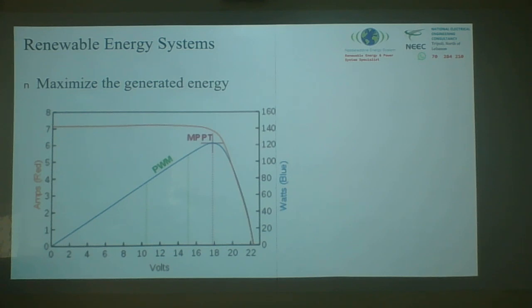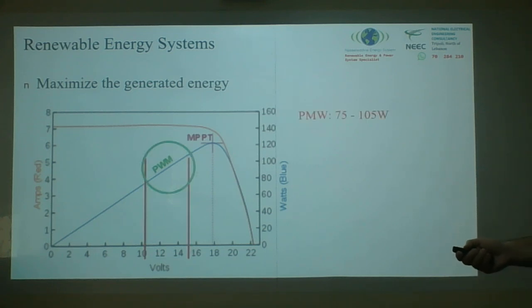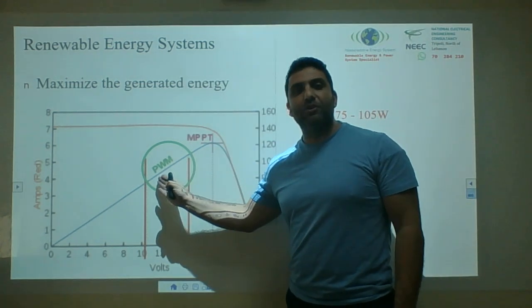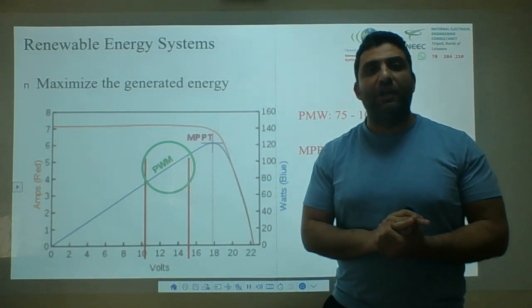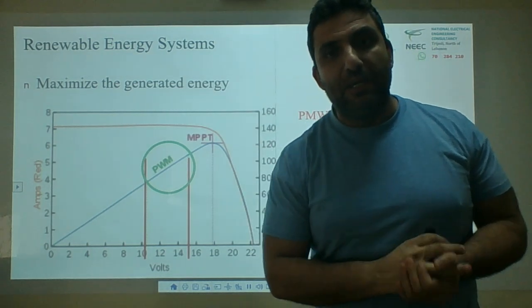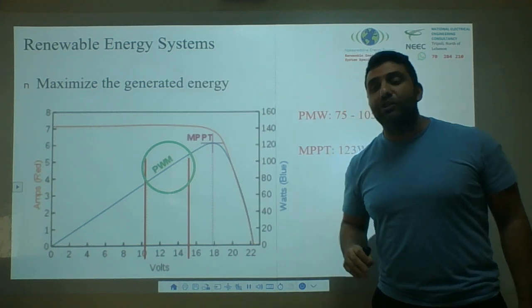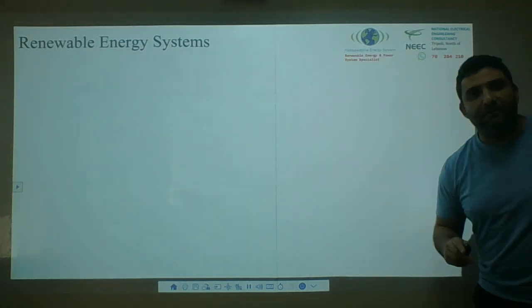Whenever you want to buy a hybrid inverter, a grid-connected inverter or a standalone inverter, make sure it has the MPPT algorithm. Try to avoid pulse width modulation, PWM, because MPPT is proven to have higher output. It will harvest more sun.